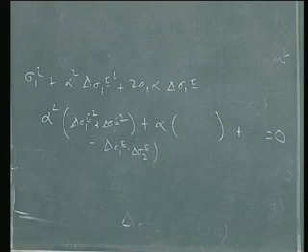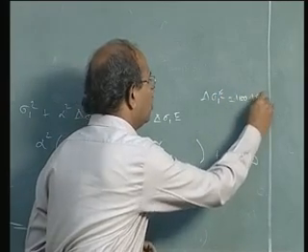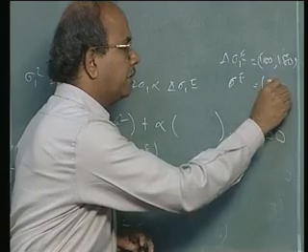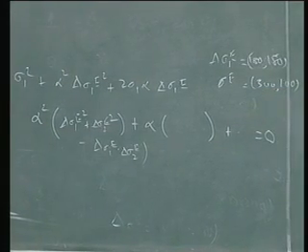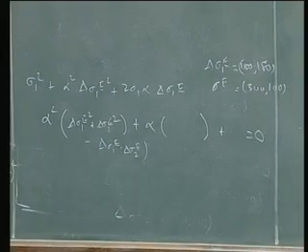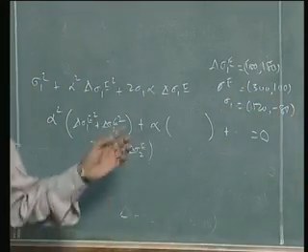Then substitute these values of delta sigma 1e and so on and tell me what would be the quadratic equation. You've forgotten delta sigma 1e 180 comma 180 and the other one, sigma e is equal to 300 comma 100, right? And sigma 1, what was sigma 1? We started with 120 comma minus 80.